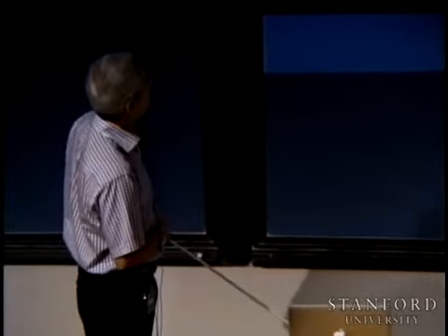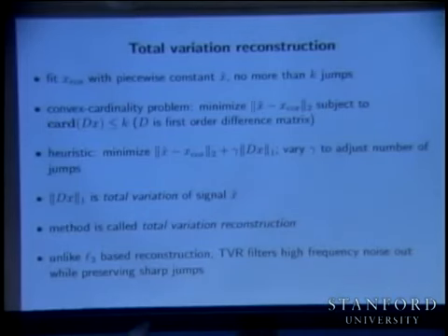A signal, that's fine. And this is called total variation reconstruction. There's a lot of things you can say about TV reconstruction, but what happens is they actually are able to remove high frequency noise without smoothing it out. And we'll see how that works. Like an L2 regularization would just give you a low pass filter and it'll smooth everything out.